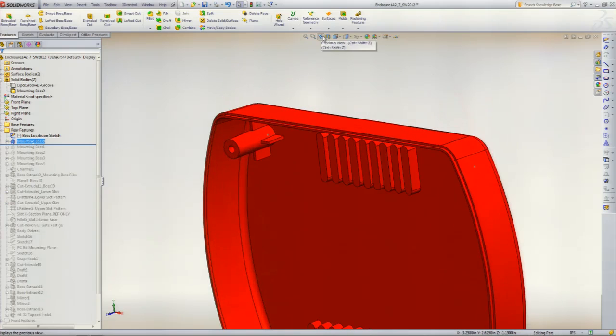Now to come up with a, yes? By selecting the vertex on that radius. Right. If you happen to change the radius, wouldn't you get an error? Oh, I would say that if you have a tangent point like that with a different size fillet, it would use that as a reference. But it's not a sure thing. I would have to try playing with that. That's a good question. You can pick a reference sketch or some other feature that would give you the orientation that you need.